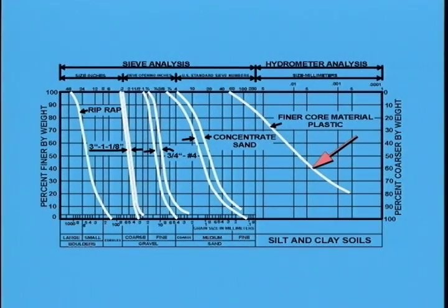For materials containing fines which are plastic, fine concrete sand makes a suitable filter, even if the grain size curve indicates that the impervious material is not self-filtering. To avoid segregation during transport and placement, filter materials coarser than concrete sand should have narrow gradations. The 100% size of the filter should be no more than 2 to 3 times the 0% size. Concrete sand can have a gradation much wider than this because when placed damp, it has enough apparent cohesion to keep it from segregating. Generally, our current knowledge is adequate for us to design proper filters. The principles need to be thoughtfully applied. Care must be exercised to ensure that segregation of materials does not occur during construction.